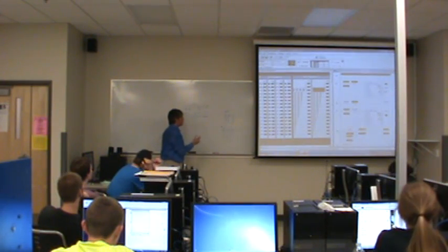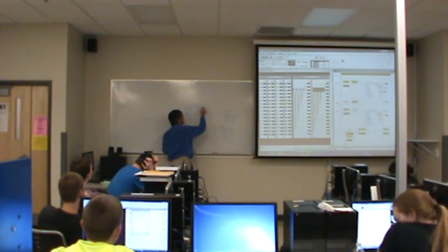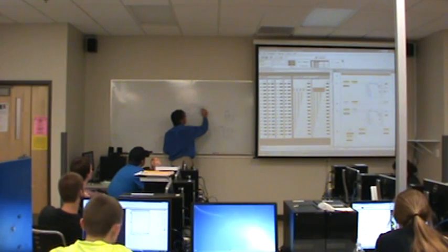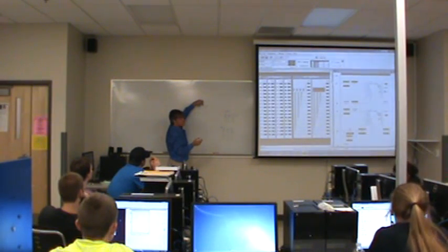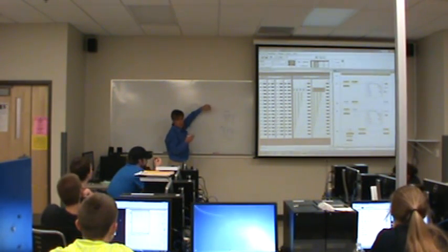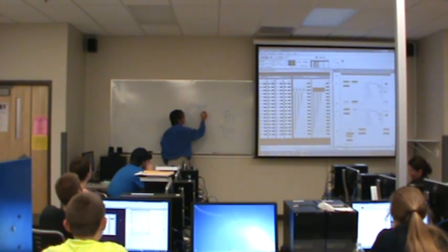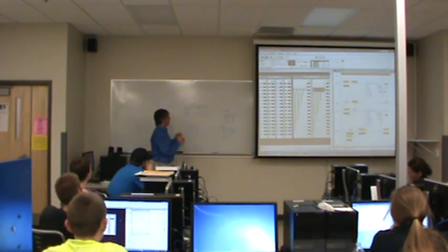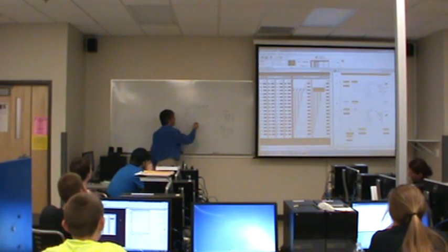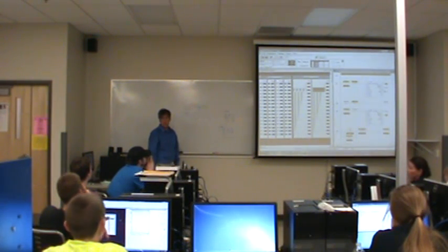So it will perform an AND. AND is really good at forcing things to turn off. Now, just for example, let's say that we have a 0 here as an input, and a 0 here as an input. Okay, so sensor 6, which I'm interested in, is on. Sensors 4 and 3, which I'm interested in, are both off. Sensor 0, which I'm interested in, is on. Now, the mask here will AND, so 1 and 1 are 1. 0 and 0 are 0. 1 and 0 are 0. 0 and 1 are 0. 0, 0, 1, 0. And so the only ones that can pass through the mask are inputs that I'm interested in. Does that make sense? Everything else will be forced off.